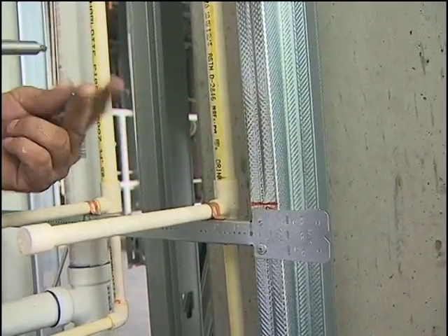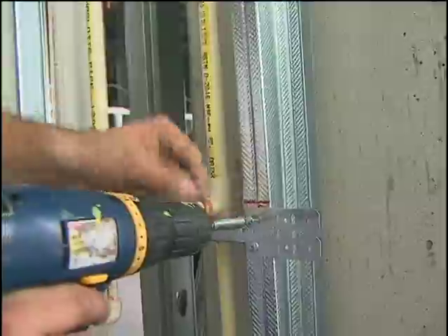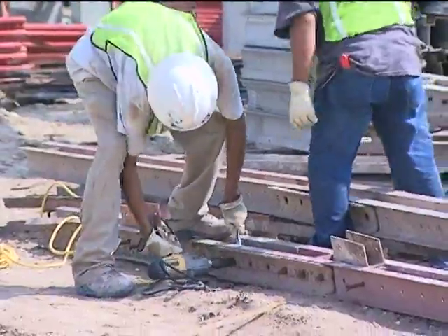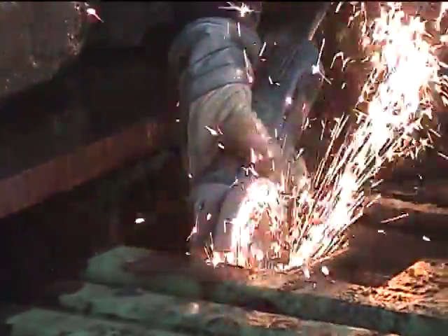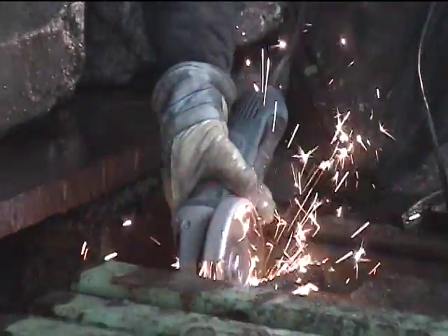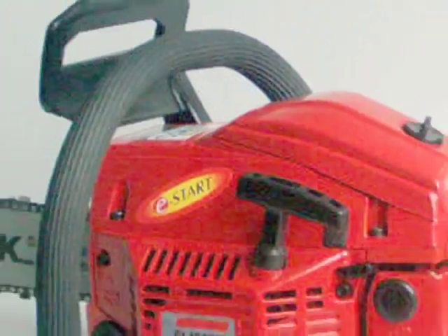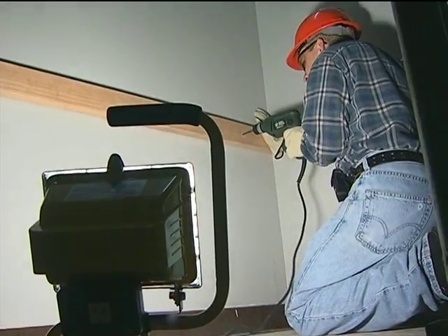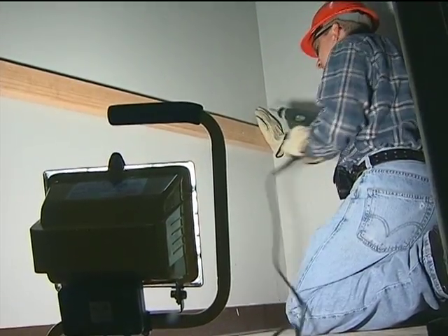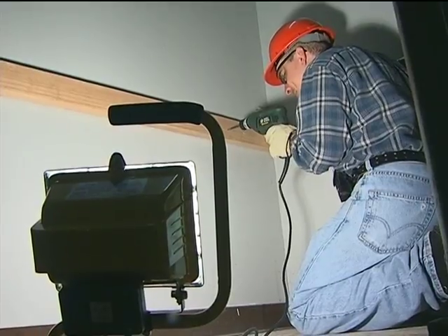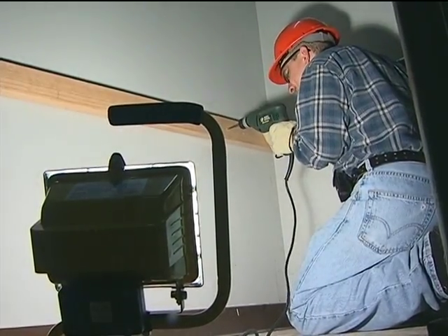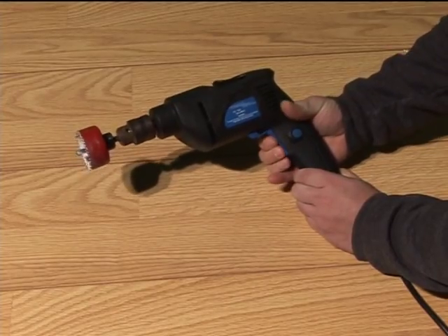Tools that must be equipped with this safety switch are drills, tappers, fastener drives, horizontal, vertical, and angle grinders with wheels more than 2 inches in diameter, disc sanders, reciprocating saws, saber saws, and similar tools. These tools can be equipped with a lock-on control only if it allows the worker to also shut off the control in a single motion using the same finger or fingers.